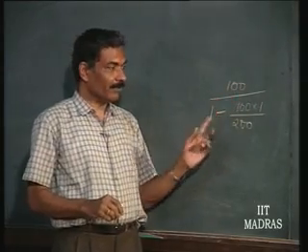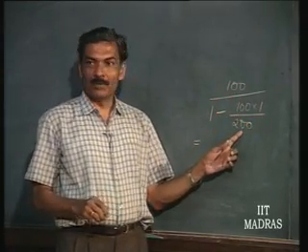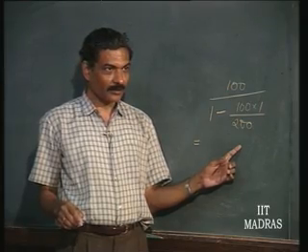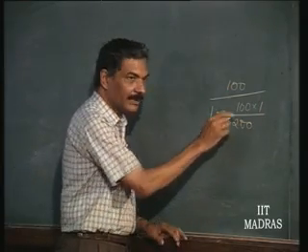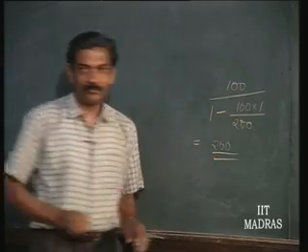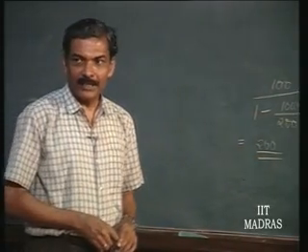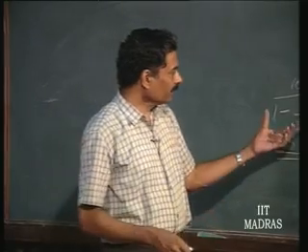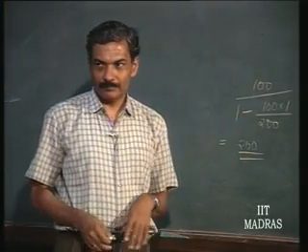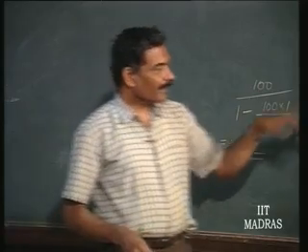This is A by 1 minus A into beta. Amount of positive feedback is 1 by 200, okay, very small. So, I have been able to make the gain now go to 200, double the gain by using little bit of positive feedback. Now, that is what is done.